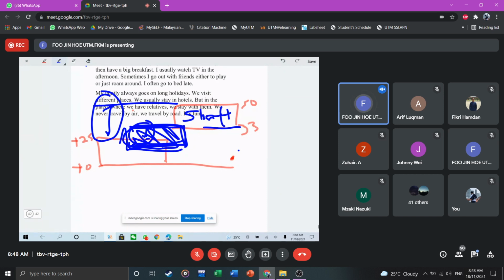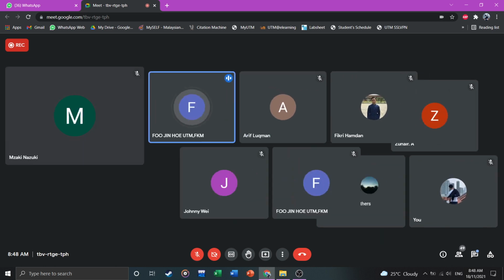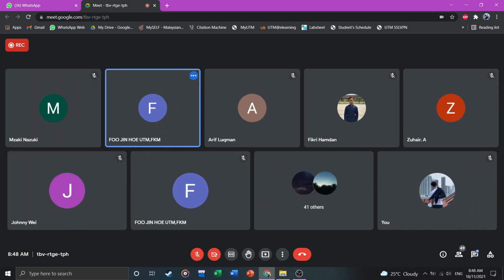Okay, so actually if I want to shift it, I put it aside to make you see a clearer picture, so that you can see clearly that the shaft is always on a higher level, or on a lower level, or at the same level. That would determine whether it's a clearance, an interference, or a transition. All right. Okay, I'll stop sharing for this one, and then we go back to the video. All right.